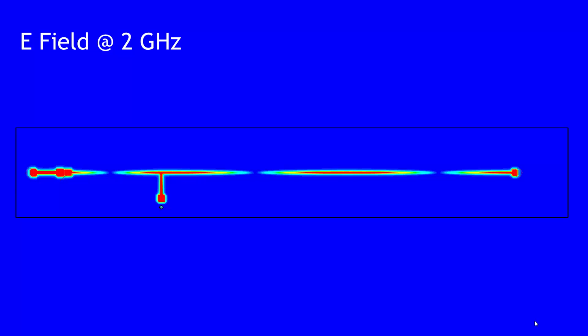The only thing you can do is this: a voltage is always something which is measured between 2 points. You need to make sure that these points are very close to each other, otherwise the voltage at higher frequencies is no longer independent from the path.